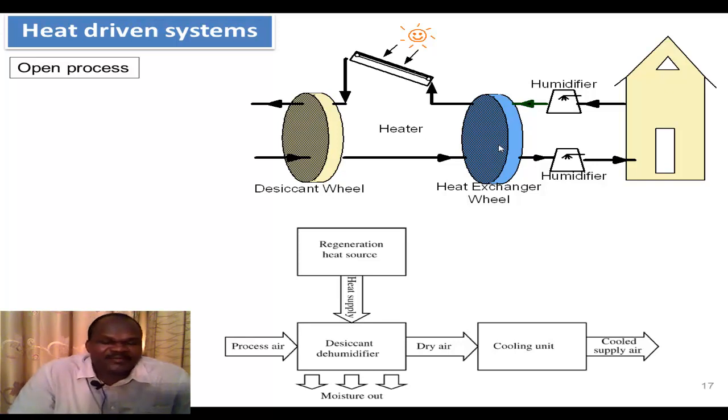In very dry climates, like Saudi Arabia and Burkina Faso, they use a lot of evaporative cooling because the air is dry, the air can absorb moisture, and doing so, the air cools down. You just put some water somewhere and a fan blows through that water, putting some water into the air. The water evaporates and takes the heat from the surroundings, so the air is kind of cool.